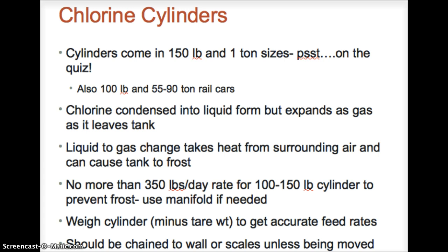To get your accurate feed rates, you need to weigh the cylinder and then minus out the tare weight, or the weight of the cylinder itself. And for safety and just to prevent accidents, the cylinder should be chained to wall or scales unless they're being moved.